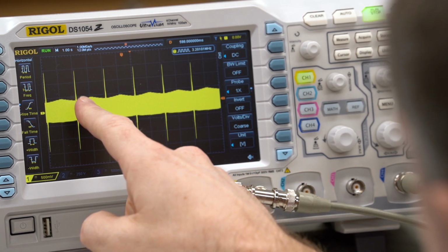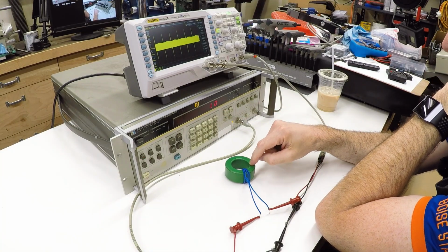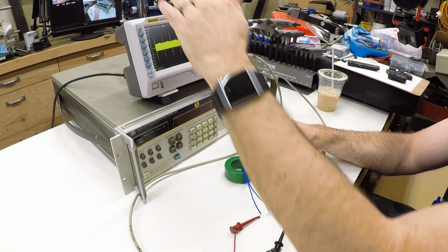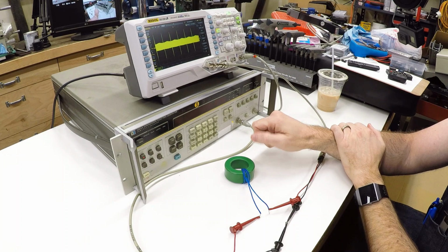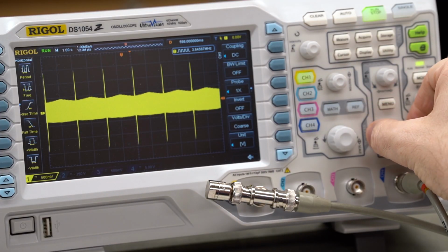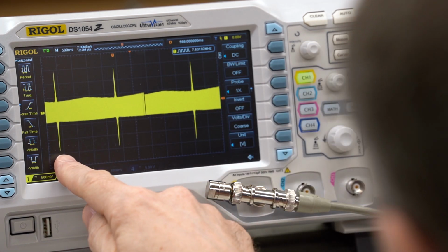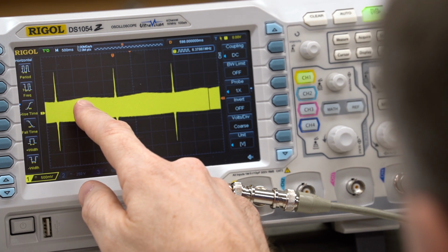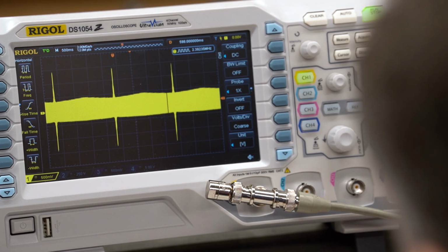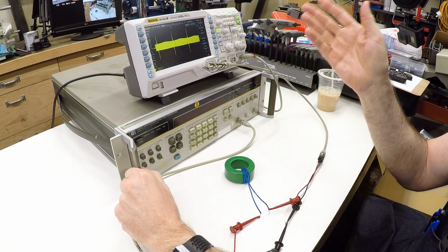And what you're seeing here is the spike at low frequency, because remember, at low frequency, the full signal amplitude is passed through the filter, and as the frequency goes up, the amplitude goes down because the filter is blocking the high frequencies. So we can see several cycles here, and I can pull this down so we see a couple. So what's happening is we're starting at low frequency, it's sweeping up to the highest frequency, and then sweeping back down, because that's how the linear sweep in this function generator works, by sweeping up and down and then up and down.